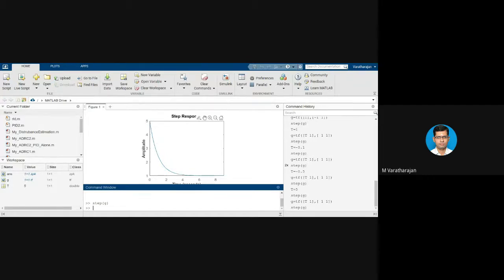The 0 of the system adds some amount of differential of your output, and it will affect the transient response of the system, but it will not affect the steady state. Whatever may be the value of t you put in the numerator, finally it will settle at 1. But the starting point will arbitrarily vary. This is the effect of 0. So this is the second task in our experiment.